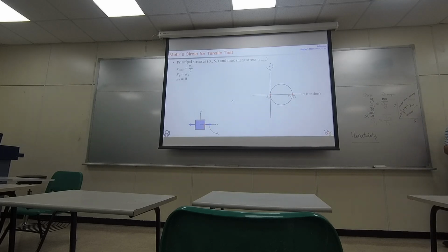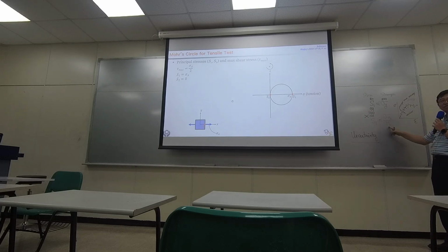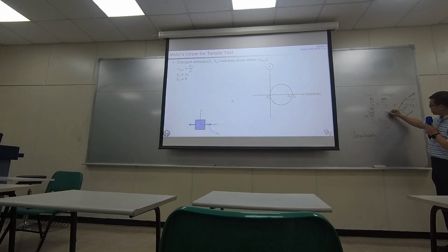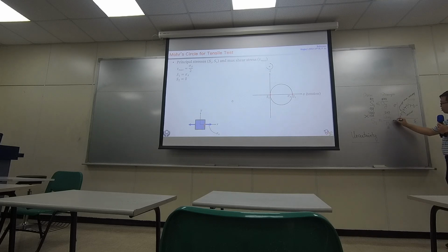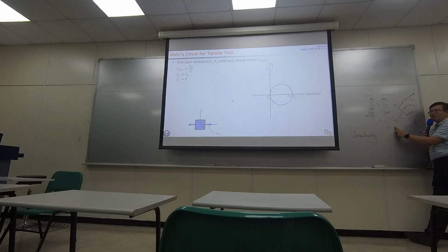We want to keep a kind of safe margin. If the safety factor is 1, it's basically the same equation. But if I say I want my safety factor to be 2, and I know the average yield strength is 100, what's going to happen? The value right here is 50. When you do this, that means you only allow the stress to be as large as 50.